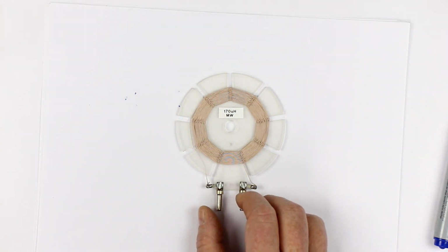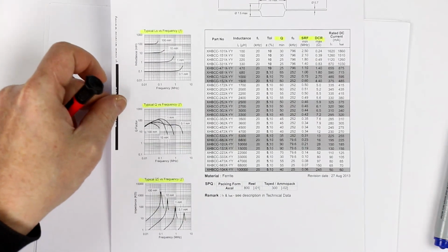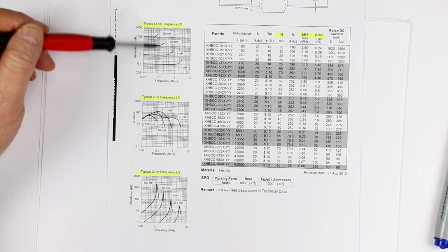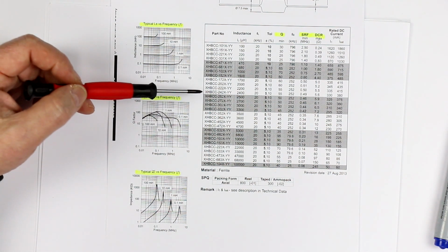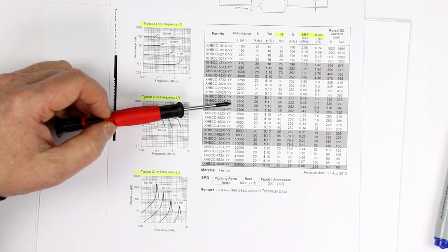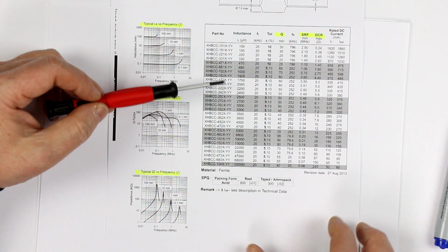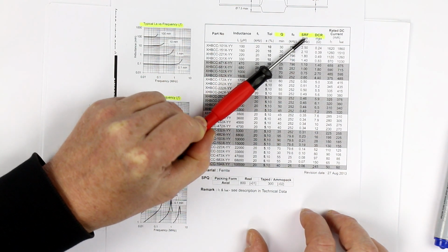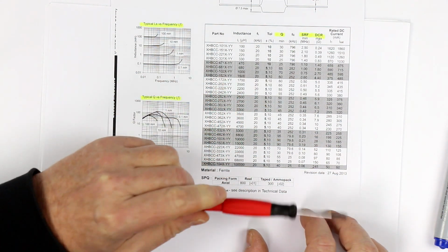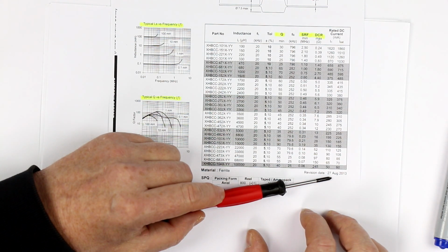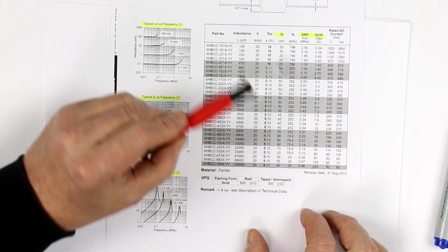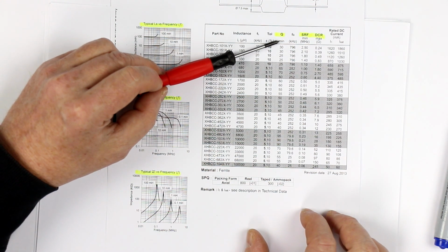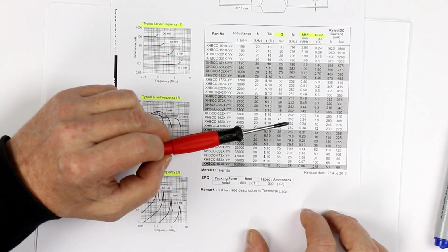Now, if we are lucky and we have a quality supplier and you know which kind of inductance you have, you can get the data from the data sheet. But what do you do if you have an unknown inductance or inductivity? Is there an easy way to measure as well the series resonant frequency or parallel resonant frequency and the Q factor? Well, yes, there is, and therefore let's take a look again at what we saw at the beginning, how we build up our test setup to measure Q factor as well as series resonant frequency.